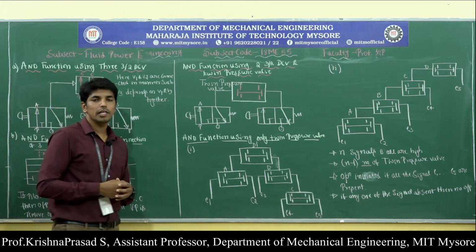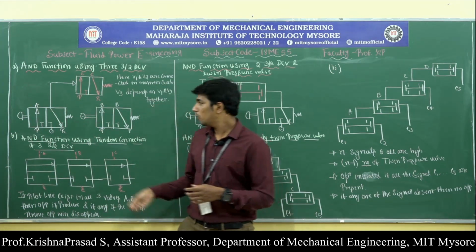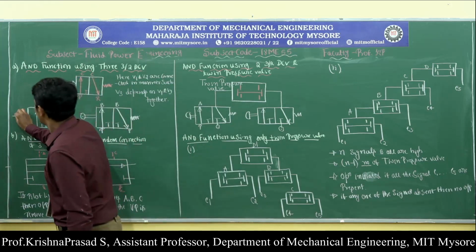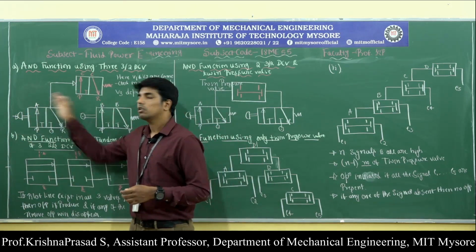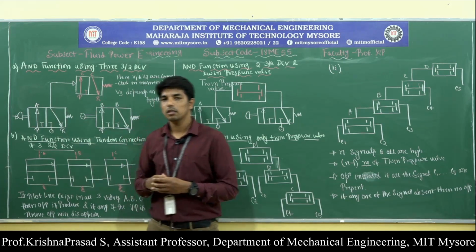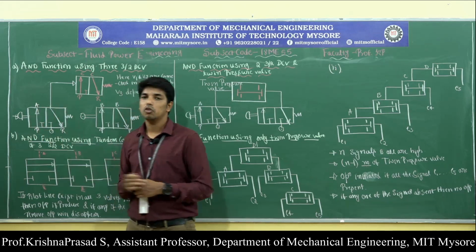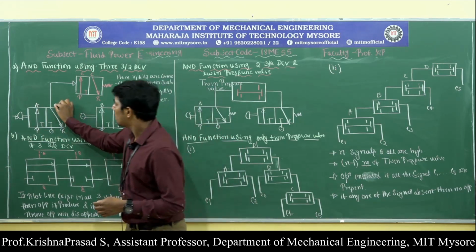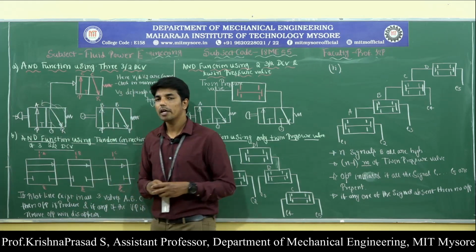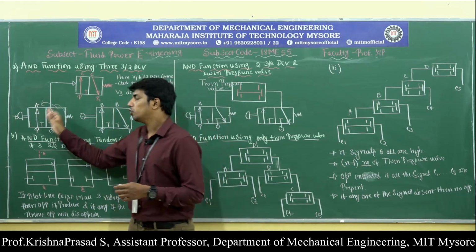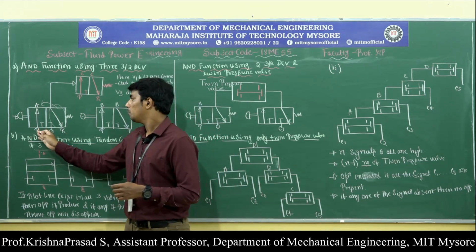Next, very important: if the push button is operated for valve 1, then what happens? This 3x2 direction control valve shifts from the normally closed position to the normally open position.